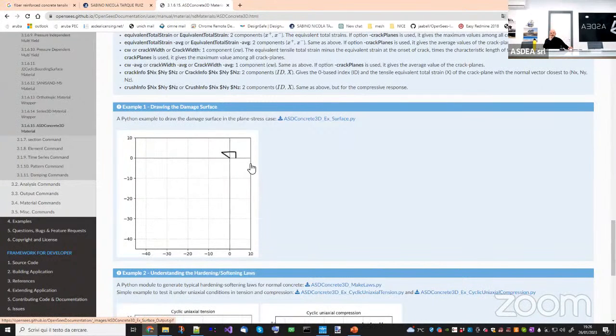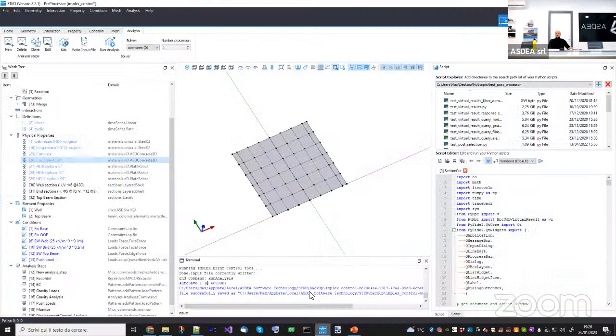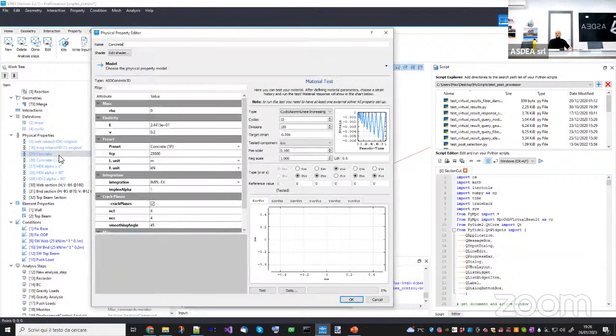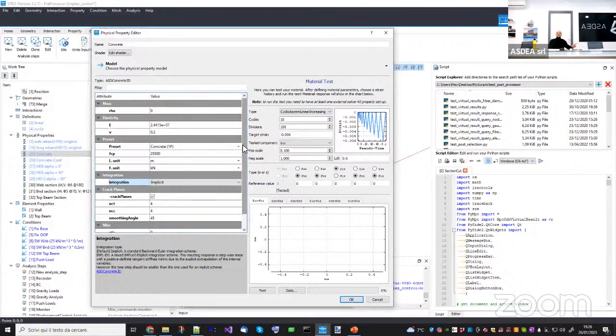But when you have stresses in the tension-compression quadrant, very close to tension only, it will not damage the compressive surface. This is a major improvement, and together with the plasticity, it will give you the behavior that generates the pinching in the cyclic test.